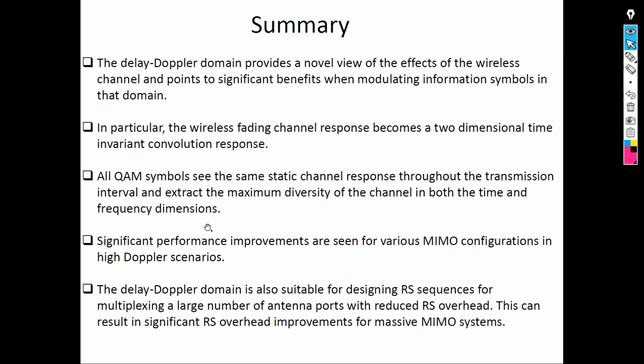That's possible also when you have Doppler, you beat OFDM, because Doppler is the enemy of OFDM, and this scheme is very friendly with Doppler. Think of it like this: this scheme likes Doppler. It benefits this scheme. Doppler gives it gain. In OFDM, it just degrades, and doesn't compete anymore when there is Doppler, if you don't have a complex receiver to detect Doppler and eliminate it.